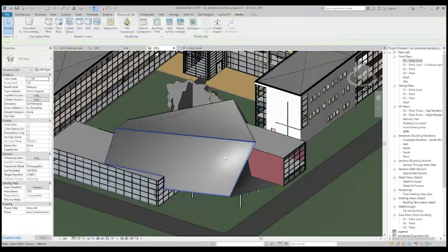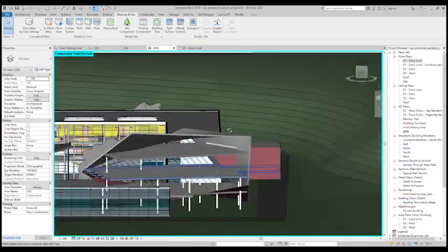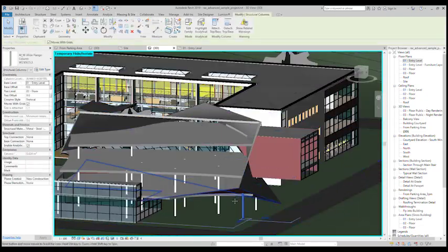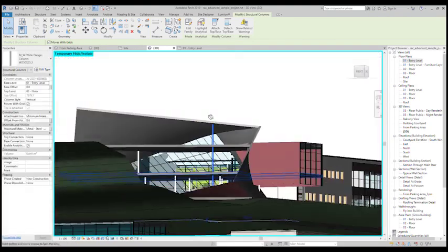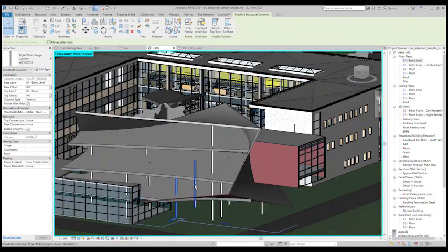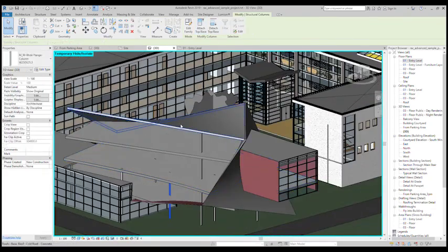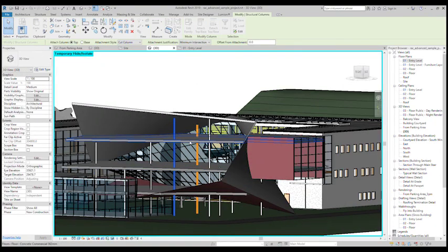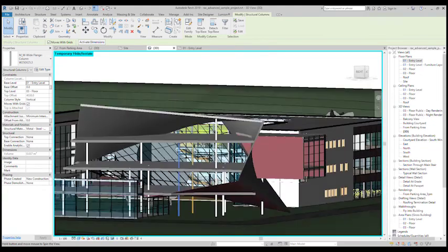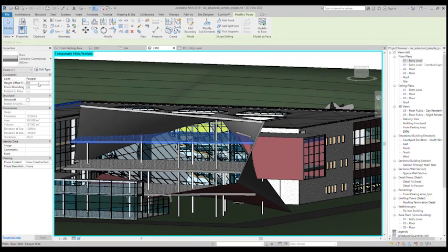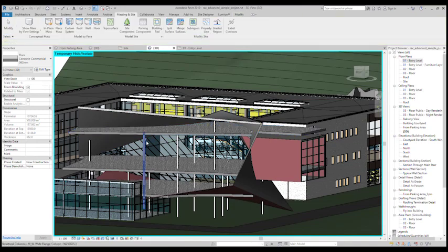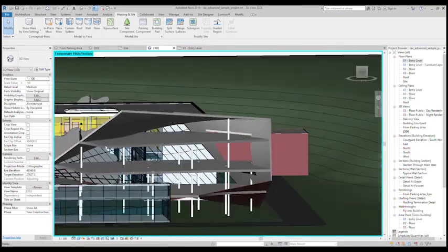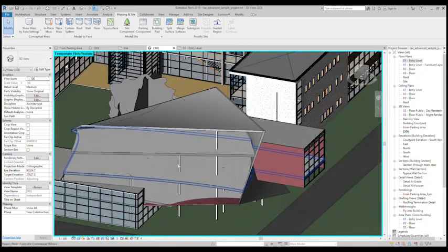And if I hide that wall, just for now, you can see that the column should be attaching to that roof whenever you move it underneath that roof. Now all of these actually have to go up to that roof, or you can attach them to specific floors. And if that floor changes, so if for example I move this floor around like 1500 upwards, you see that the attached columns move upwards with it, which is really neat to do. So that's the basic rule of columns.